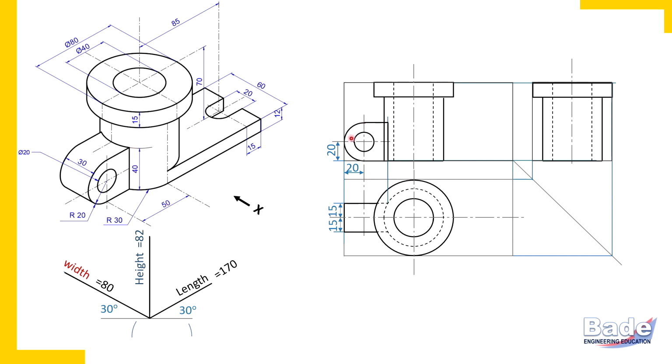So the U-shaped block is complete in the front view, but remember you never get two visible edges intersecting in an orthographic view. So there is a mistake and a correction is required. Can you tell me what that correction is? Now listen. The cylindrical surface, this dotted line in the top view is the cylindrical surface, but watch in the front view.